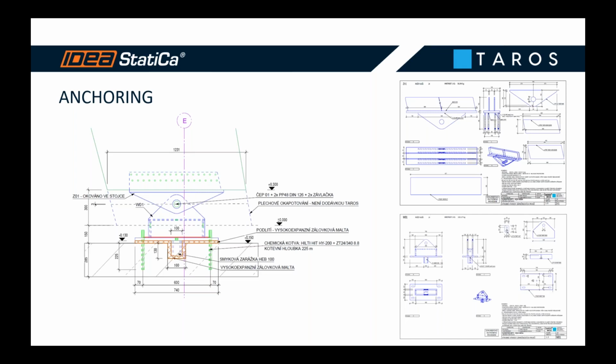It was made from 2 parts. One was fixed to the timber column in a factory. Another one was fixed to the concrete substructure on site. There was a shear lock, and it was fixed by chemical anchors, and together it was joined using a pin. On the right, you can see the original shop drawings of those two parts.